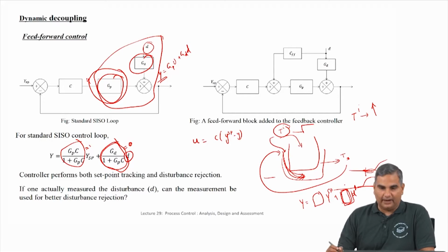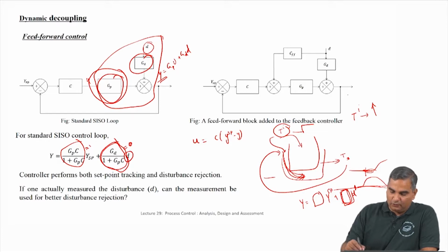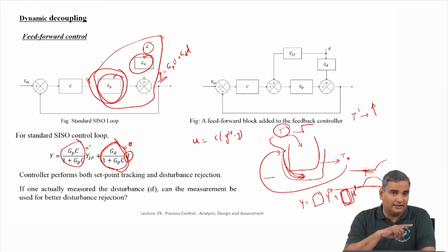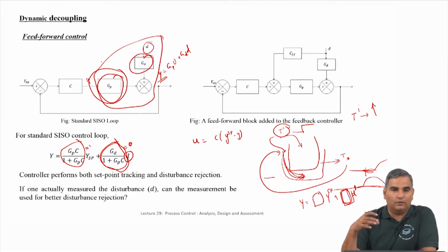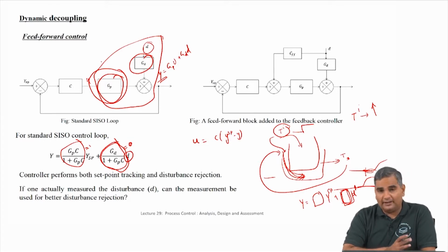Now, this physical idea of the feed forward controller, when we put it into a block diagram, again notice something interesting. This is your standard feedback loop, right? If there is no measurement of D, nothing happens here, but once you have more information, in the cascade control case we started measuring the stem position, that is more information. In this case we assume that the disturbance is measured, that is more information. So, whenever there is more information, the key idea is, how do I modify the closed loop diagram to accommodate this information, so that the controller is better, the control is better? That is the key question that we asked in cascade control, and the same question is what we are asking in feed forward control also. Without any extra information, there is nothing you can do.